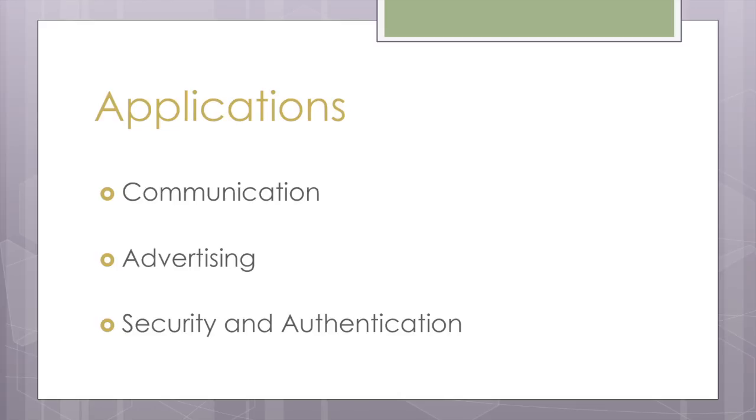For security and authentication, the University of California in LA is using the Leon 2 soft processor for their ThumbPod prototype. This prototype is an FPGA-based prototype using Leon 2 on a Xilinx Virtex-II field-programmable gate array. This prototype also has 2 coprocessors. The main core processor runs the embedded Java kilobyte virtual machine to help with the software development. The purpose of this prototype is to capture a fingerprint, extract the features, compare to a known template, and return with a matching score from 0 to 100.